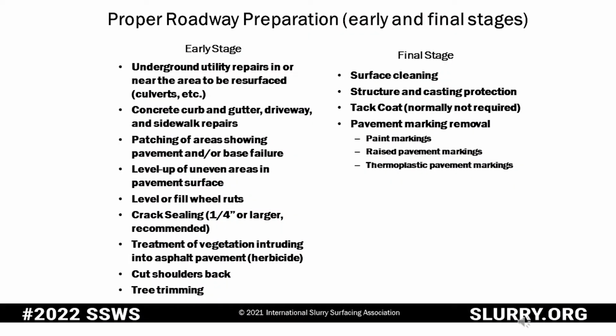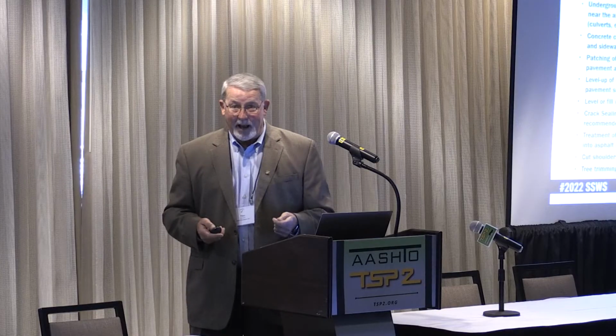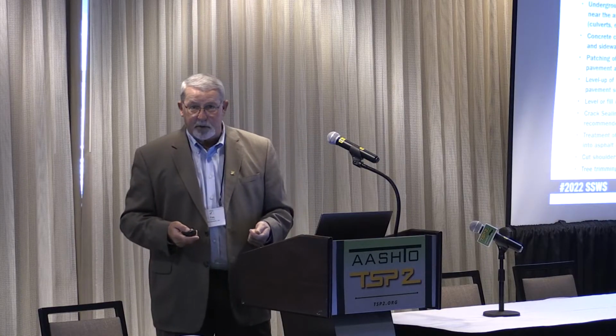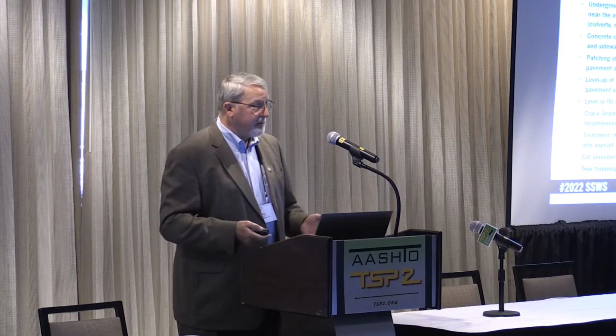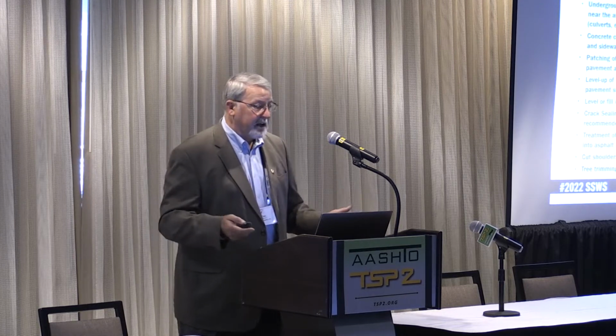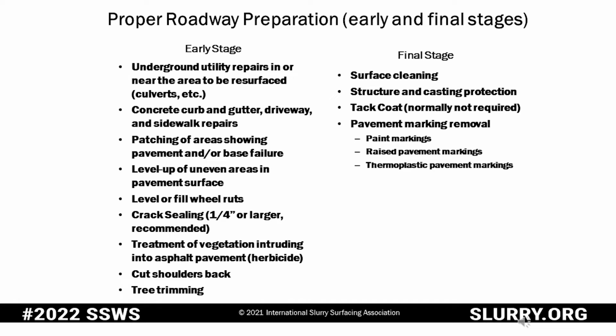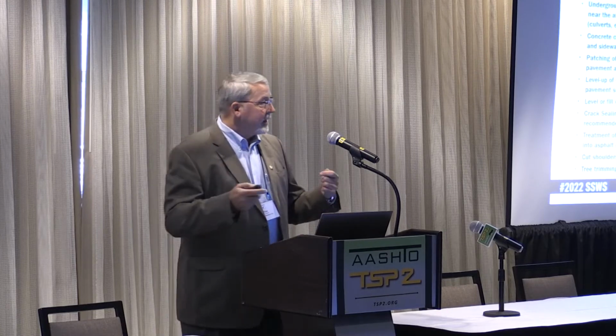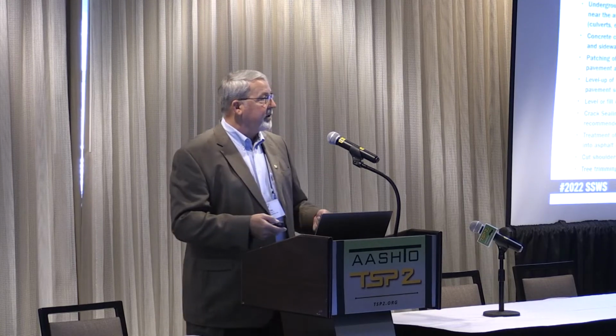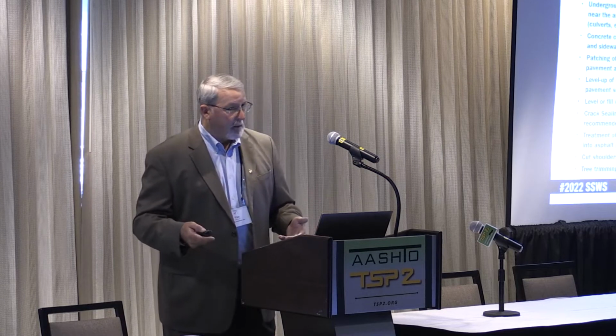Final stage stuff, surface cleaning. It's extremely important that we maintain a bond with these thin treatments because that's what we rely upon for performance. If we can't bond to that pavement, we will not perform, guaranteed. Structure and casting protection, whether it be a drain inlet or a catch basin or a water valve cover, a manhole, you have to cover those, mark them, get back and open those things up after the material's cured. Prior to opening it up to traffic, you're going to be a lot better off.